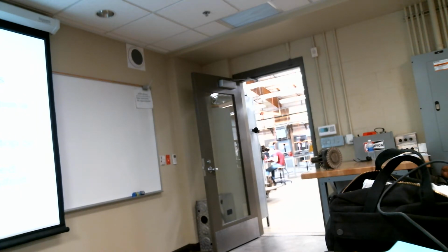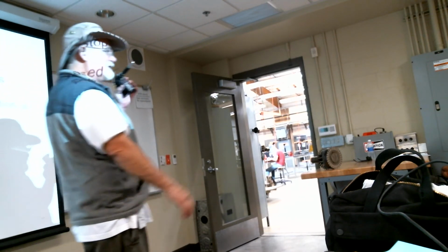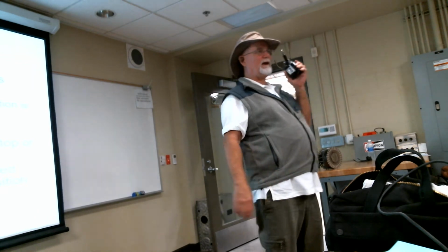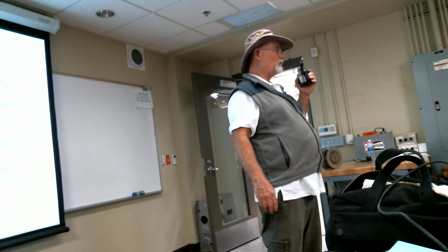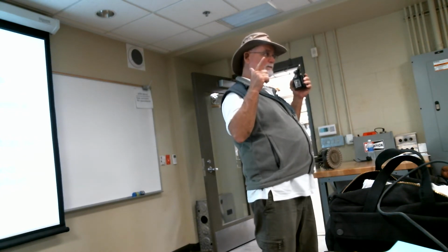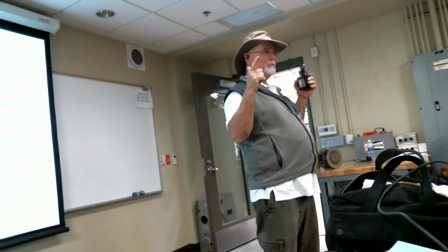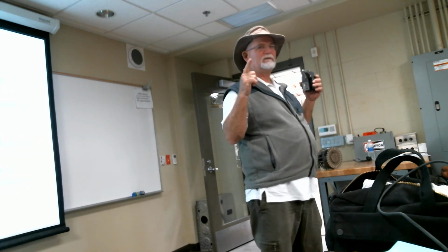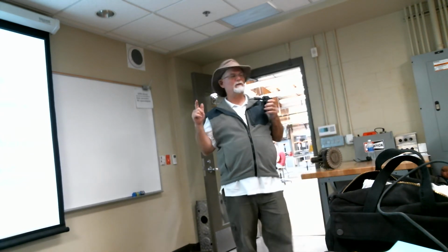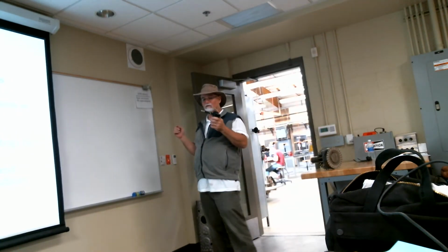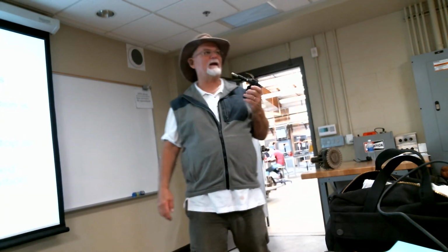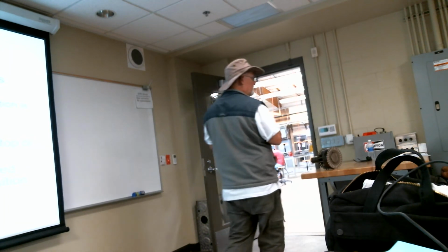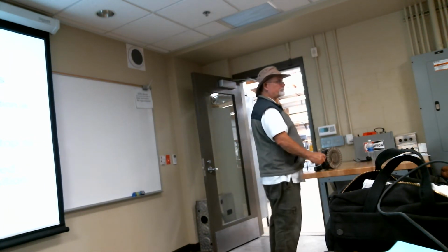Okay, but we don't care where it's at. This guy, though, is driving the flaps out. We do care what position it's in, right? And we actually want it to go to some point and stop. We don't want to keep putting the flaps down to the point the plane crashes, or suck the flaps up to the point that something breaks. So precision begins to matter. Where precision begins to matter, we start using the term servo motor.